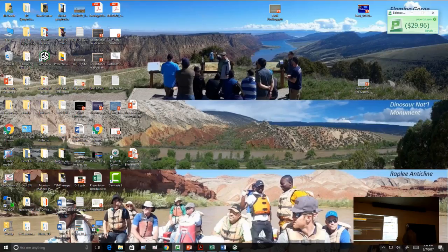This one's built to follow this manual for the most part. So the next thing we have to choose says interpretation project. Next arrow, just choose all data. So we're just going to work our way down this list right now. We chose the OpenWorks project, and now we're going to choose interpretation. We say just take all the data. What is our measurement system? This project is in the North Sea, off the coast of Norway, so our project's going to be in what units probably? Metric. There's something called SPE preferred metric. We're going to choose that one. Now we can choose to display our data in time, like seismic data, or in depth. We're going to choose time to get started.